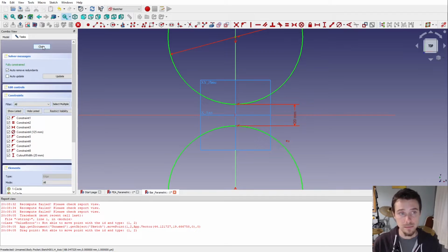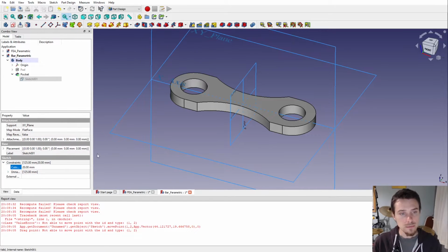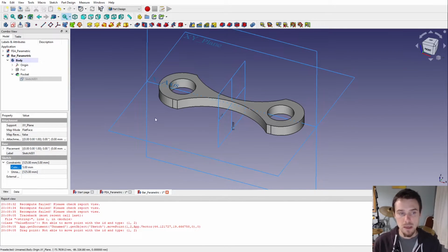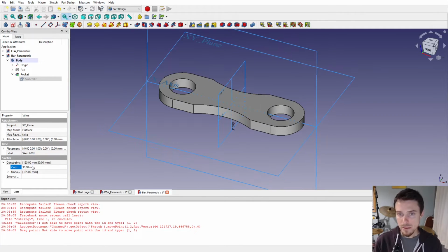When you rename it, 2 things will happen. One is that name will stay. Also, if you click on Sketch, you open constraints, the constraint that you have just created will come out of the unnamed block. So on unnamed, you'll see all the constraints. So one thing I can do straight from here is I can set this to 5mm, and the parameter changes straight away. I can set this to 30mm, and again, this is pretty much instantaneous.